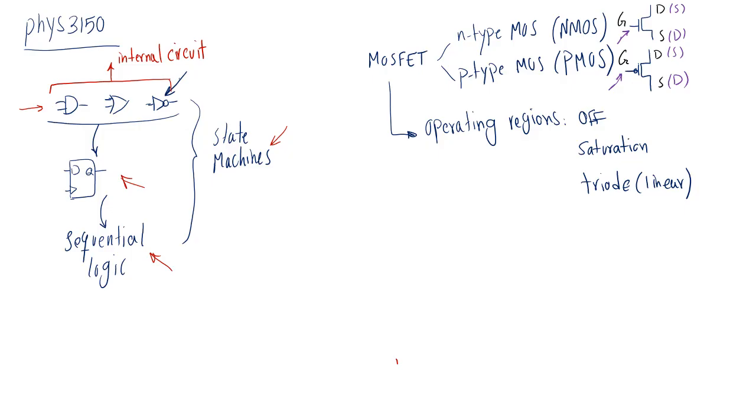So this is the most useful region. The saturation region is the most useful region of operation for MOSFETs if we are using MOSFETs in analog circuits and if you want to use them as amplifiers. So the best, well, not the best, because best might imply that the other regions might actually be useful. It's actually the useful region in analog